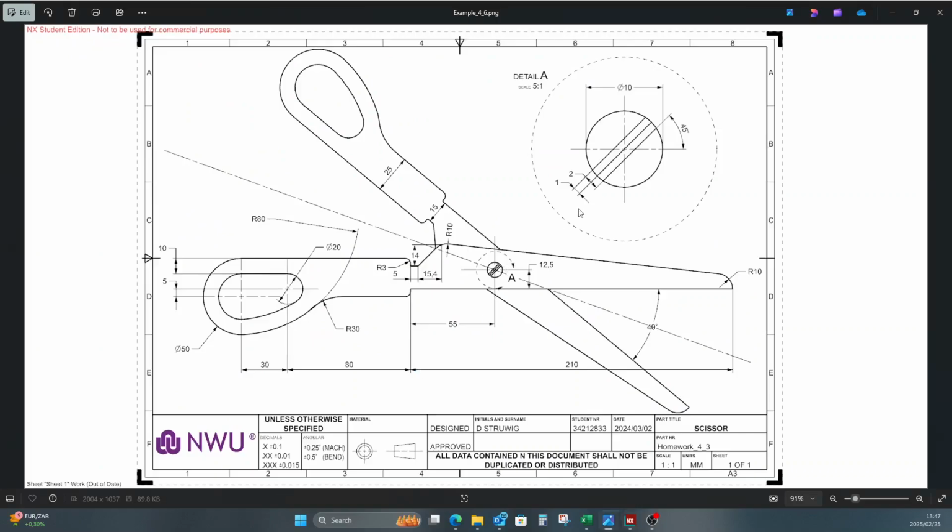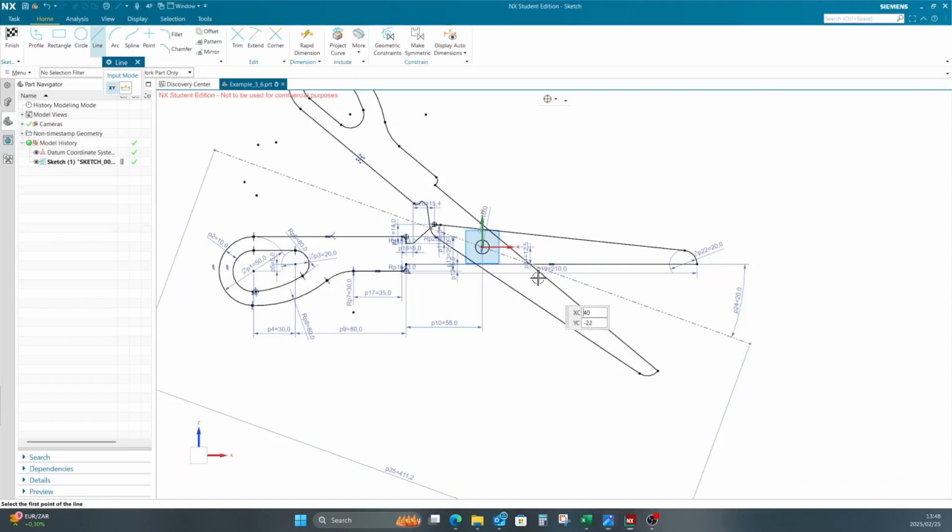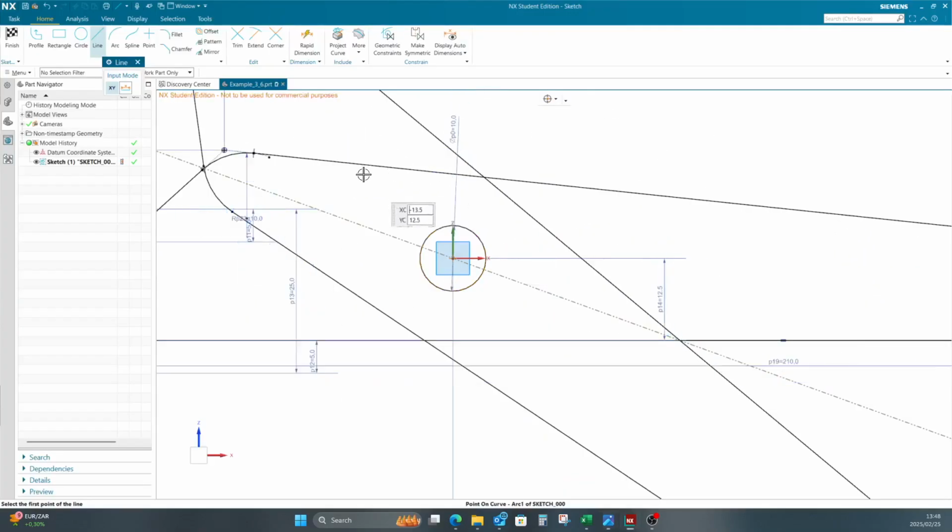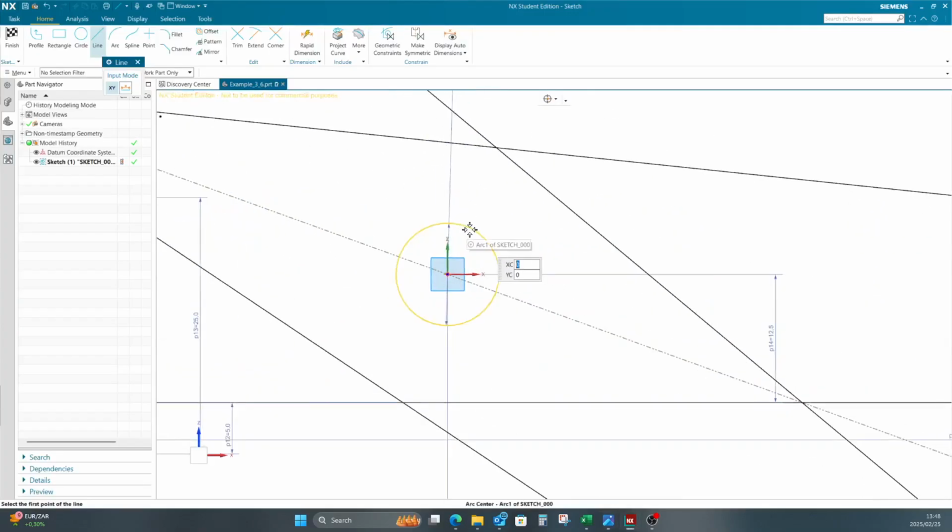Add in those two lines. So that angle of 45 from that horizontal, 2 millimeters and 1 millimeter. So that's over constraining. Well, actually, it's not. You need that because I didn't say it's in the center. But yeah, so let's just add that line quickly. There's one going through the center point, so it's on that arc.